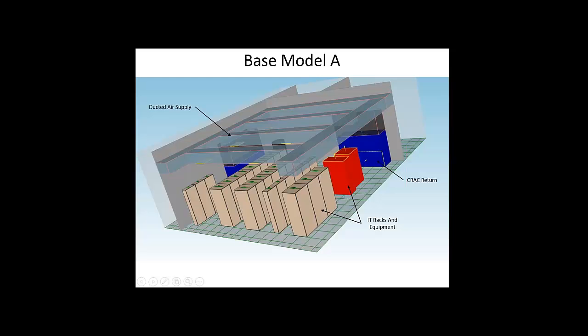This is a shot from the CoolSim 4.4 modeler. This is what the model creation process looks like. You see here the racks. The green indicates direction of airflow. These are front to back. You can see this is a hot aisle here. Here's another hot aisle here. This one's kind of a mess over here. It's blowing into this one. So guess what? Not everything is perfect in these data centers.